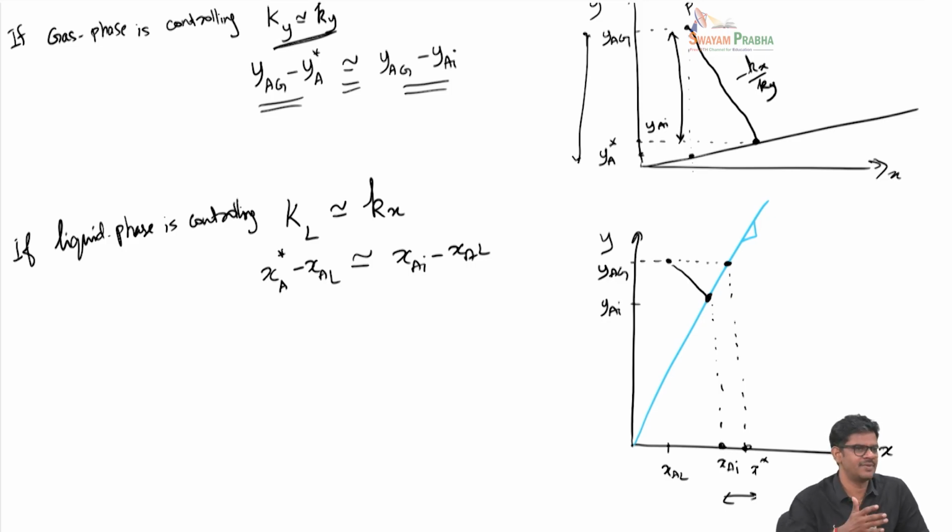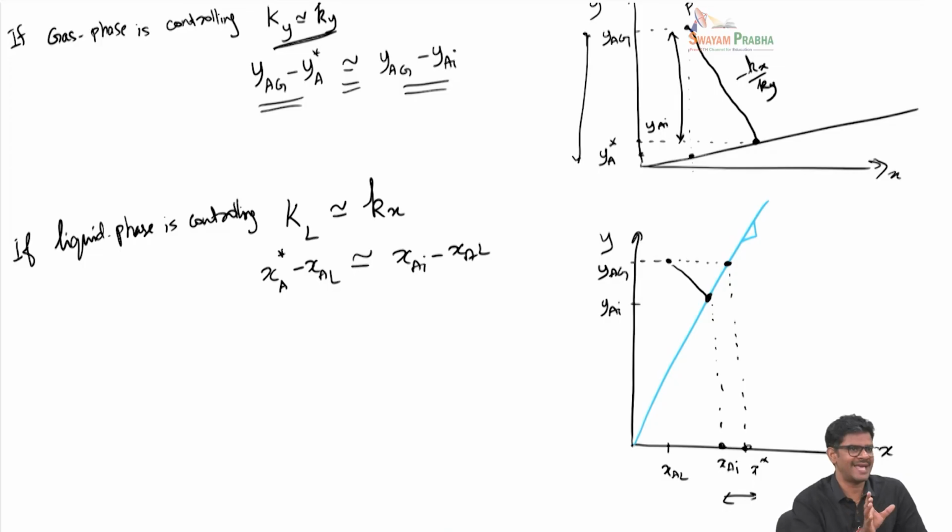But the idea is the same. I can give you a kind of curved equilibrium line, and then for those particular interfacial concentration and the equilibrium concentration in that particular segment, you find the slope. You can define the slope along the curve, and then you can decide. So I'm talking about two different classes of gases. One is very sparingly soluble, another is very highly soluble. They can be characterized based on different slopes.